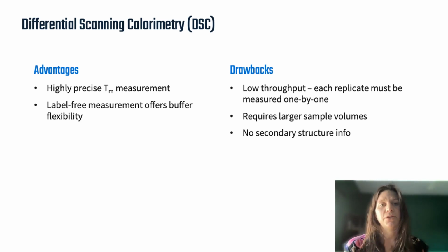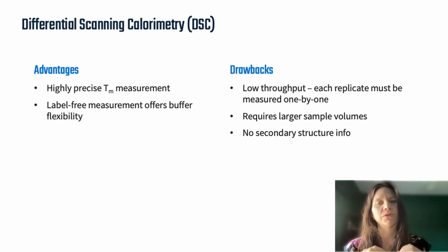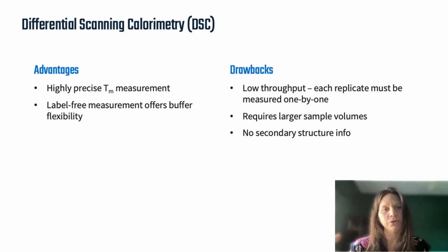Now, while the sensitivity and temperature range of DSC is a huge boon to material science researchers, it's actually less necessary in biologics. It's not really needed to profile a biologic outside of 20 to maybe 100 degrees centigrade, and very rarely are researchers working with such low sample concentrations that it's difficult to tease the signal from the noise. DSC instrumentation also scans each degree change in temperature slowly, meaning it can actually take quite a while to run a single experiment, and since you don't have high throughput, it ends up taking you a long time to gather all the data you need on every single candidate or condition you're screening.